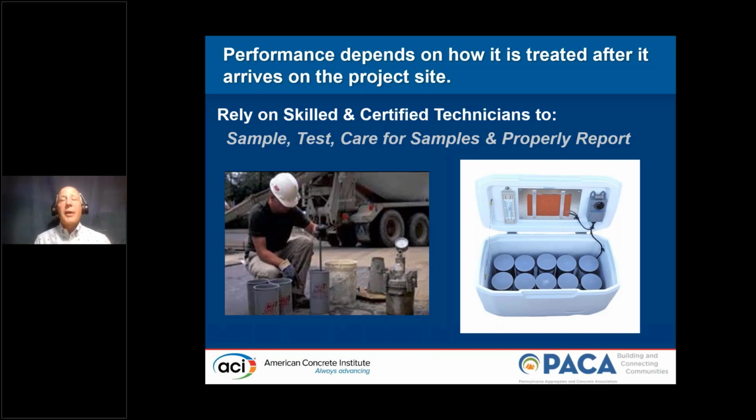And when he's done making his cylinders, he's going to put them in a facility that maintains the curing temperatures, initial cure, while it's on the job site. This is what we expect. This is what is required underneath the building codes. However, there's sometimes where this system breaks down.